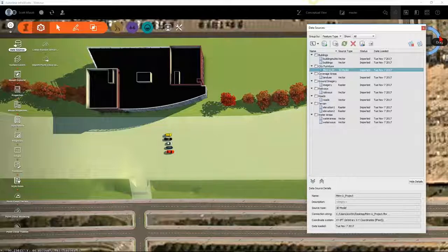The problem you have with Infraworks is once they're in, you can't really move them. You can make minor adjustments to it, but when you bring in a point cloud, make sure that they were geo-referenced before you bring them in, and then they should show up in the right northing, easting, and elevation. There were some new features in the 2018.1, which allows you to do data extraction from a point cloud.